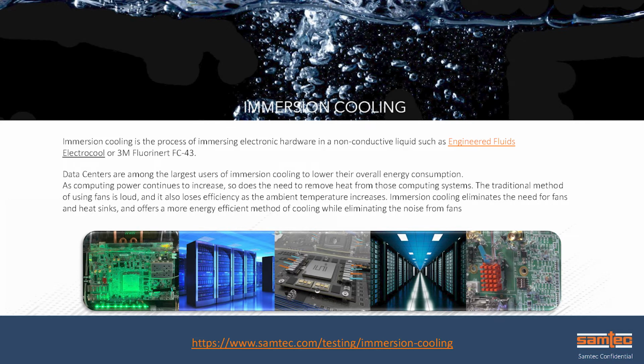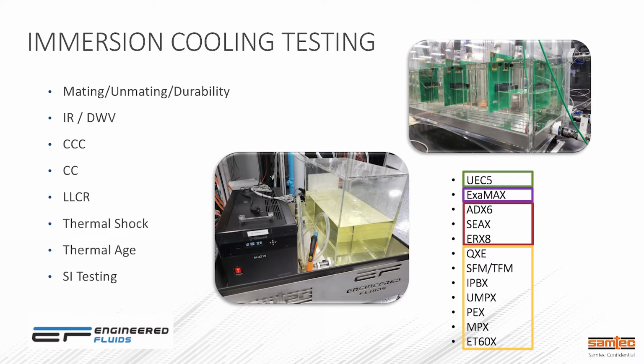So data centers are one of the larger users of immersion cooling, but it's showing up in other industries as well. So you can go to this website and find the different products that we've tested. The immersion cooling test that Samtec does includes mating and unmating durability, insulation resistance and dielectric withstanding voltage, current carrying capacity, low-level circuit resistance, thermal shock and thermal age, as well as signal integrity testing.